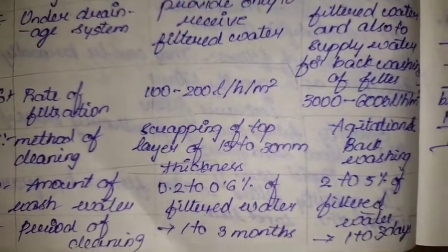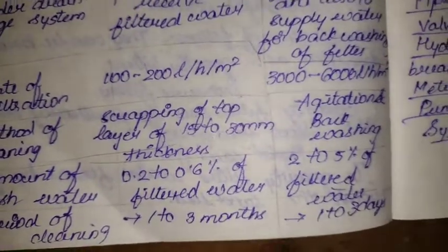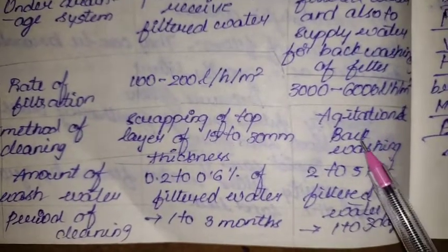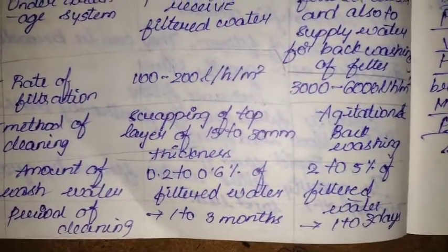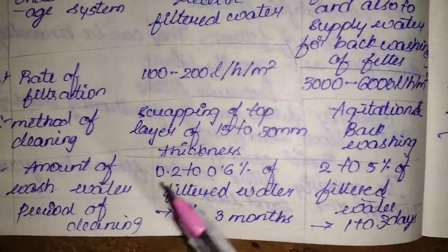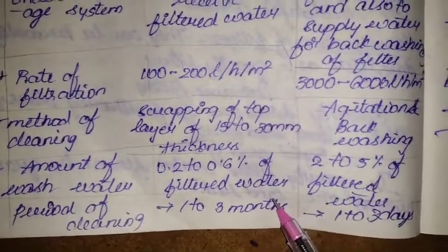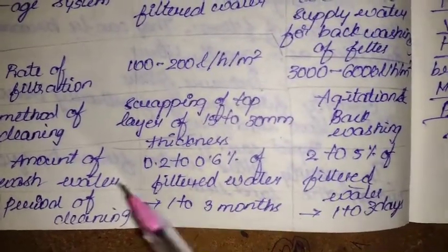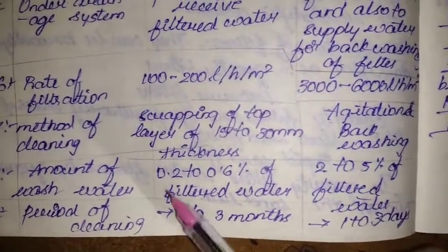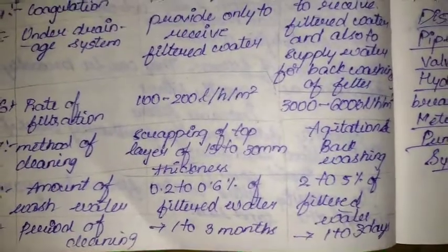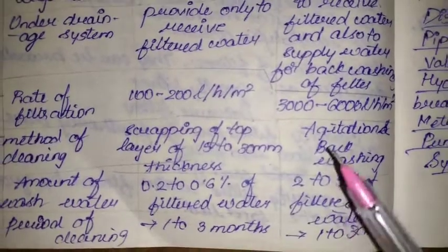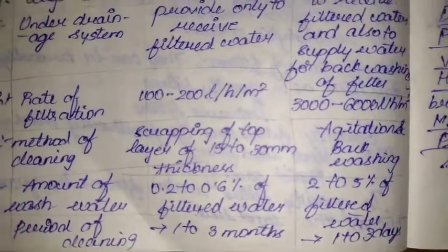Okay, so we'll just scrape off, we'll remove the top layer, that is up to 15 to 30 mm. And here we have an option called agitation or backwashing. The amount of wash water, how much of the filtered water is required to wash that filter, is this part. Let us say if we are filtering 10 liters, then 0.2 to 0.6% of these 10 liters is required to wash this, whereas in this case we require 2 to 5% of the water